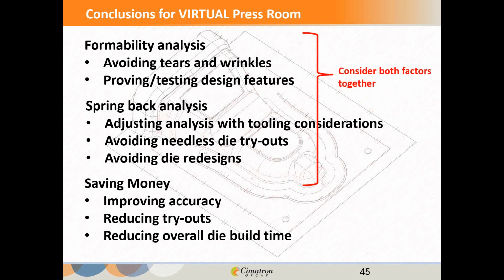I hope I've illustrated to you how one little addition in your design thinking, one addition like a draw bead or moving a pilot hole, can affect the overall outcome to your advantage or your disadvantage. But being able to prove it on the screen, you've got something that you can sit down together with and look at and say, this is the best way to go about tackling the job because we've considered this, we've considered that, and this is predictively what is going to be the best solution for our first tryout. Will it take away all die tryouts? Well, can't say that, but why not take away those that are the needless ones?